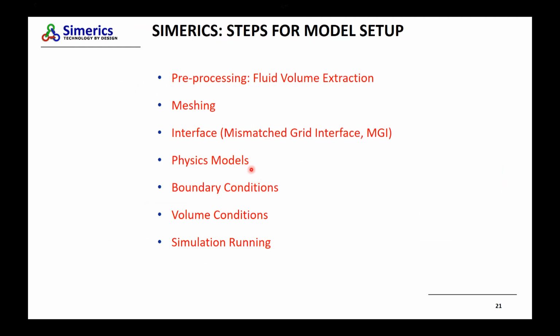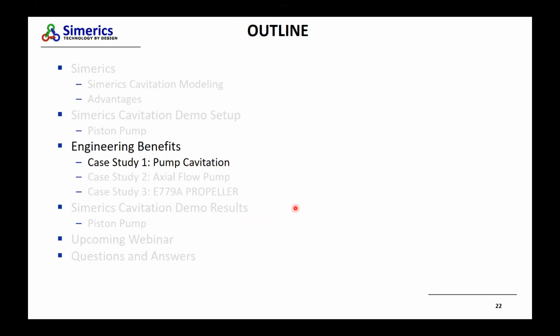And then we add the physics modules that you want to solve. In this case, cavitation is the main thing that we are looking at. And then you set up some boundary conditions and the properties and start running the simulations. So let's talk about some of the case studies.